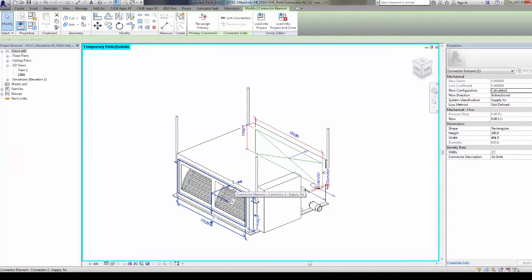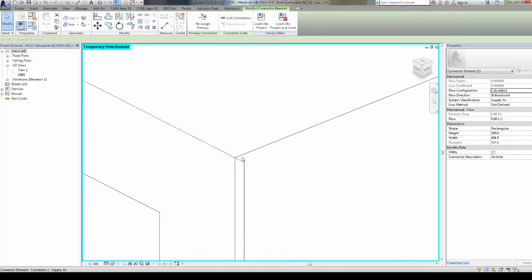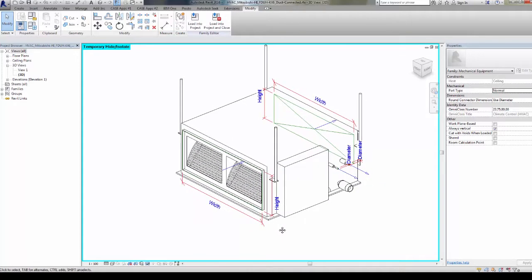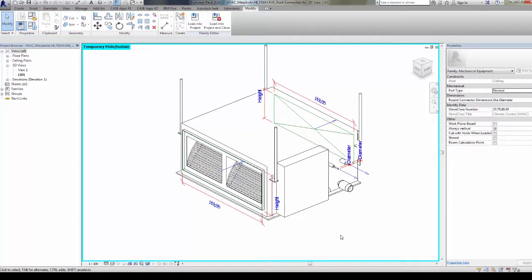It is also possible, and it is the most common case, to have connectors whose size doesn't correspond to a standard one, not corresponding exactly with the geometry. Then, the plenum dimensions will not coincide with those considered by other manufacturers' modelers. Therefore, it is necessary to firstly consider some standard dimensions, which are the plenum manufacturing ones, and so we'll see how some adjustment will have to be done. In the current example, we are doing a considerable adjustment, though in reality it will be a matter of centimeters or even millimeters in order to adjust it to the exact dimensions of the indoor unit. However, it is also possible to do the opposite, which is to adapt the indoor unit dimensions instead of the plenums.